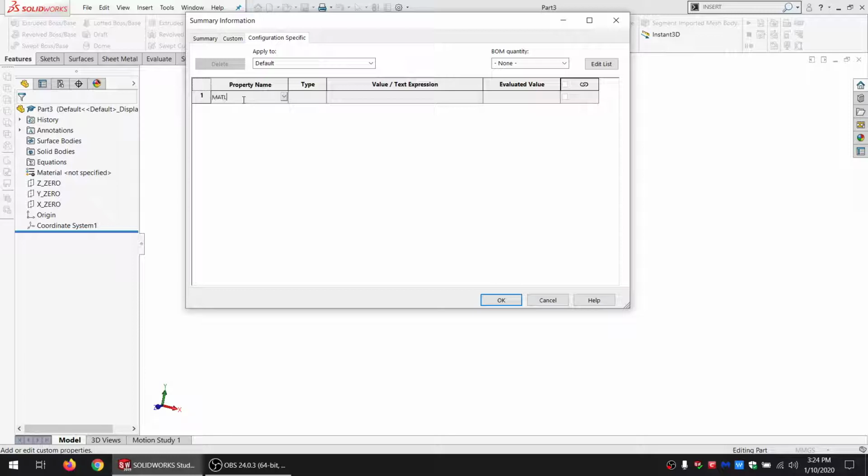So I'm going to make something called material thick. That way, if I decide to make it acrylic, that's still a logical name for it. And I'm going to call this 4.5. That's pretty close to the wood that I have on hand. I haven't measured the particular piece that I'm going to use, but that's about the average of what this stuff is.